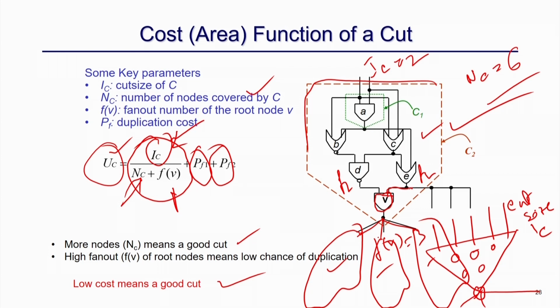and from here, this is a very important thing to notice. If there is a fan out, right, the problem is that there is no output from this cut, because a LUT has one output and k inputs, right. So, since this is my output, this output is not available once you map this cut into a single LUT. So, this is very important. But this is going to be used somewhere else, right. So, this fan out is going to be used somewhere else. So, the problem here is that this node has to be duplicated in some other cut.